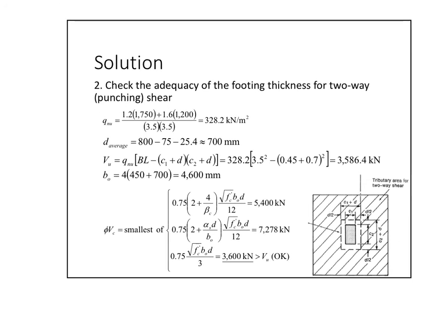Now going to the next check, which would be going to the LRFD, factored loads. I have to factor the loads, which are those here, the 4,000, and then divide it by the actual area to get QNU, Q net ultimate. It is 328.5. An important question comes here. How come my bearing capacity was 290, but what I see here is 329? So the reason is because this here is a factored load, while the other one is the allowable stress of the soil is an unfactored, or should be compared to unfactored loads.